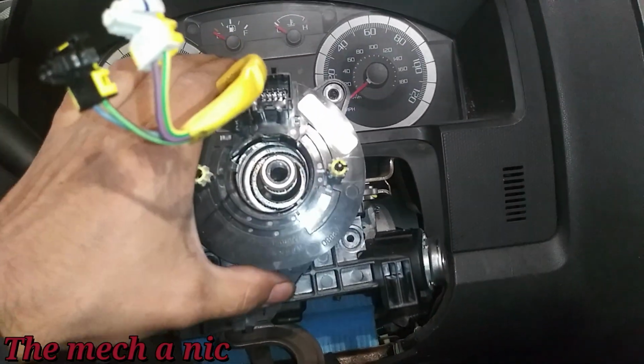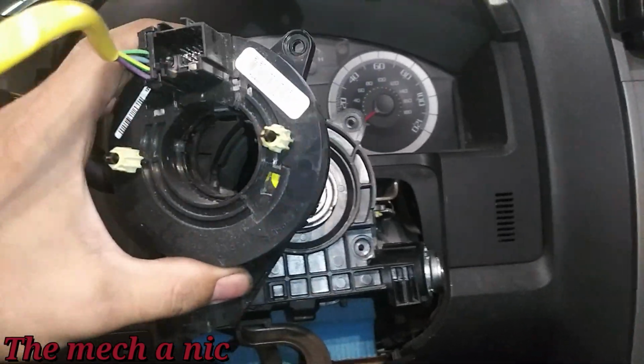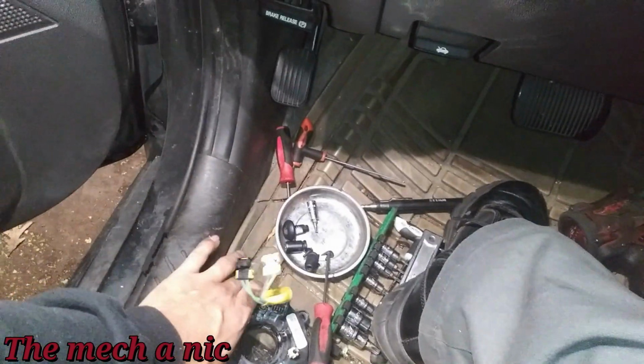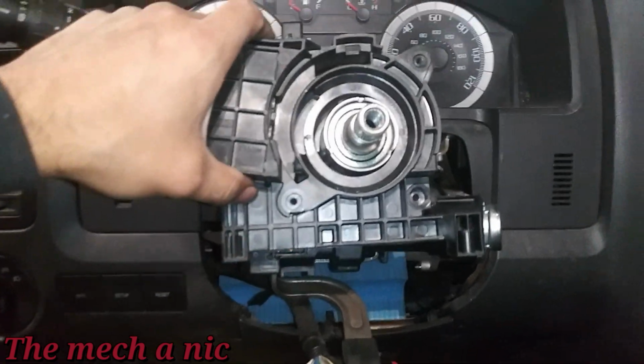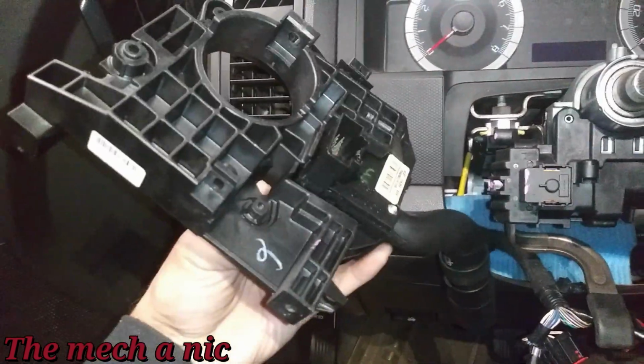Okay, so I removed the screws for the clock spring, and try not to rotate this. Just take it off directly how it sits. Again, don't rotate it, just set it aside, and remove the screws for this piece as well, which I already did, so it should pop off. And I've already unplugged everything from the back of it. There goes the wire harness just hanging right there. Let's put this aside for now.